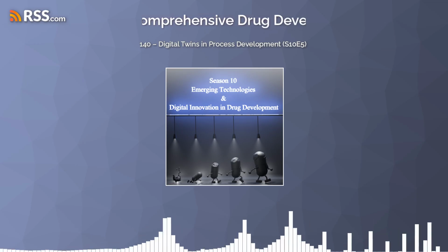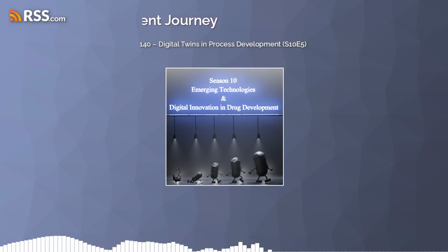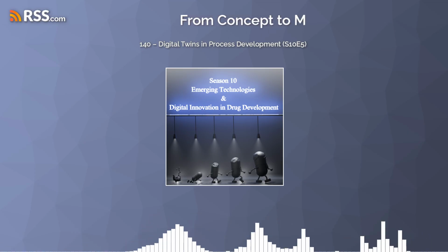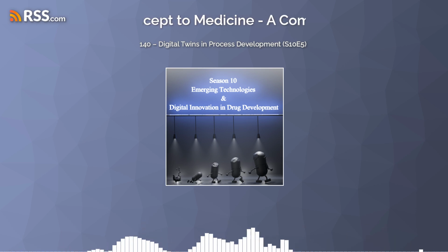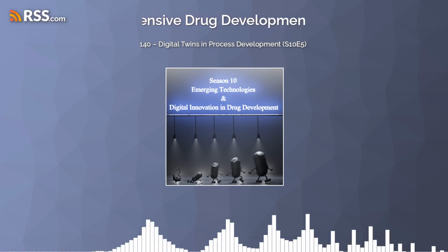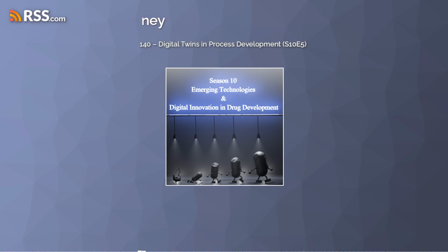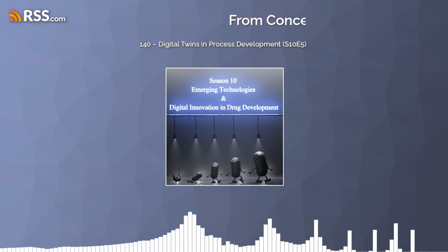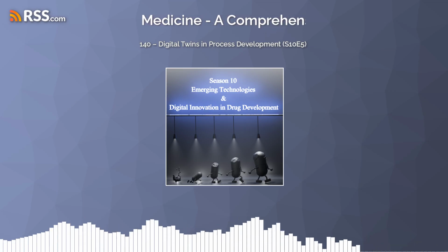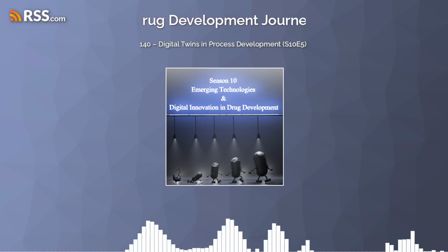They really are. And it all feeds into this bigger philosophy in pharma called quality by design, or QbD. Right, we've talked about QbD before. Building quality in from the start. Yes. And digital twins are a perfect tool for QbD. They let you define the design space virtually. The safe operating window for the process. Exactly. You can simulate how critical process parameters like that temperature or mixing speed affect the critical quality attributes of the drug, like its purity or dissolution rate, all done virtually before making large batches. So you understand the process deeply and build in robustness from day one, virtually. That's the power of it. Proactive quality assurance, driven by simulation.